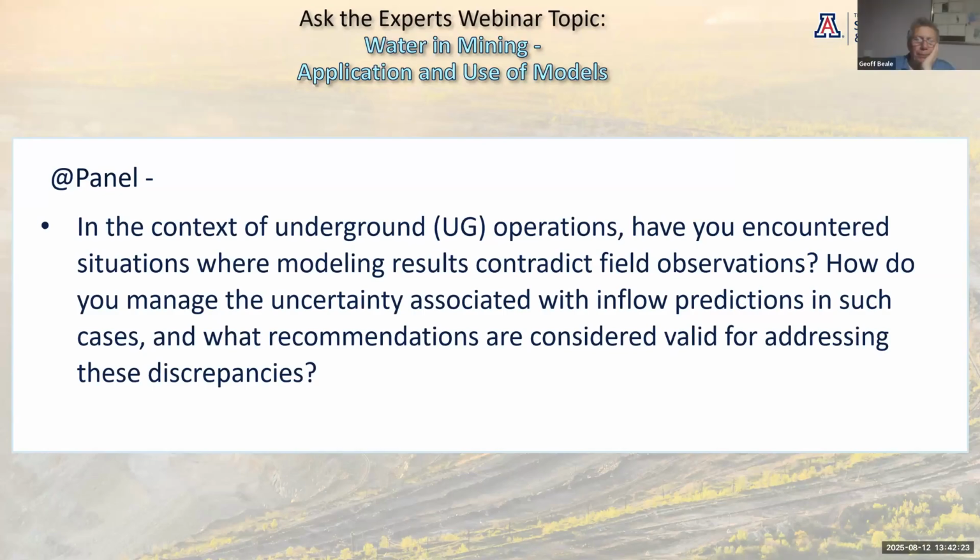So one good thing about underground is you can do cross-hole testing and pumping testing without pumps, provided you've already got an operation. Several times this week, we've been encouraging operators to drill holes with a bit of collocation, shut them in, measure the pressure, and then drill holes, allow them to flow, and watch the response. So underground cross-hole testing is kind of fundamental to understanding how much water you might get and how much your peak flows may be.